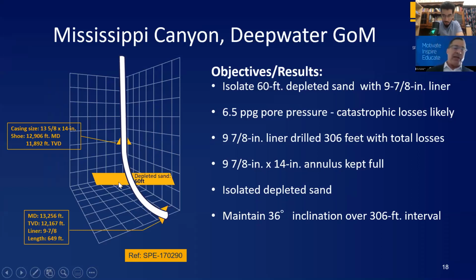So what they did, they evaluated drilling in a 9 7/8 inch 62.8 pound liner to get through this sand and set the liner in a competent shale where they would have a good fracture gradient to eliminate a potential contingency string and enable them to get to their planned TD, which is exactly what happened. The liner was a short one, about 650 feet, but they drilled it in successfully through the sand and did get it into the competent shale, but not before some problems.